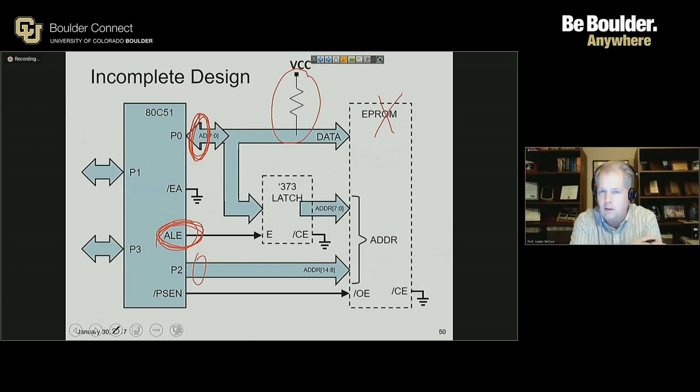You need to tune it in the design phase so that in high volume, you're just checking, did it come up right or not? And if it didn't come up right, you fix the flaw that's on the board. You don't change the component value. You just substitute a part or fix an open trace or whatever is wrong with the board. You're not changing or tuning that value again.